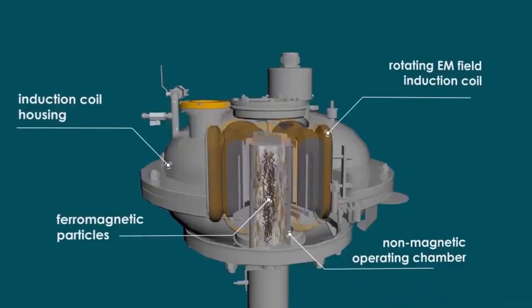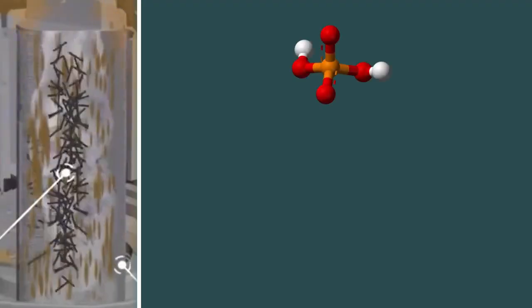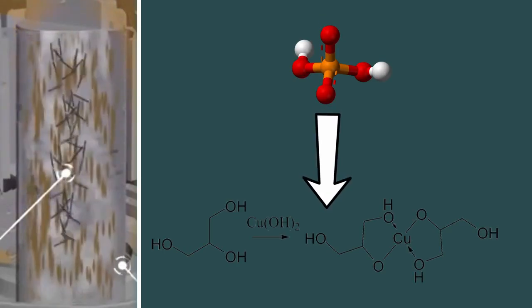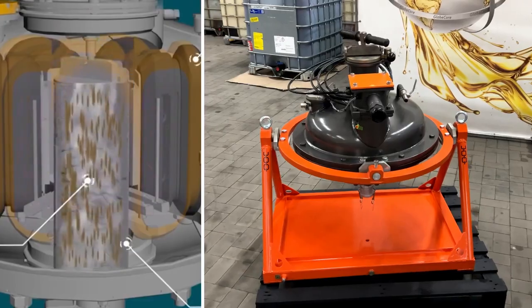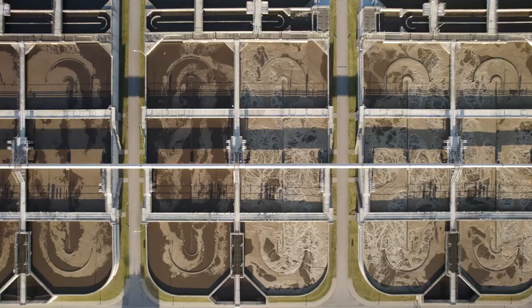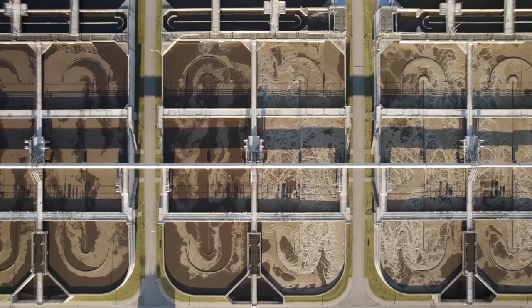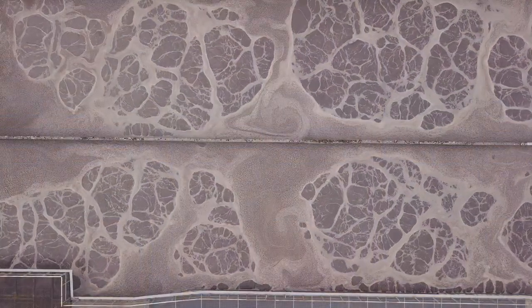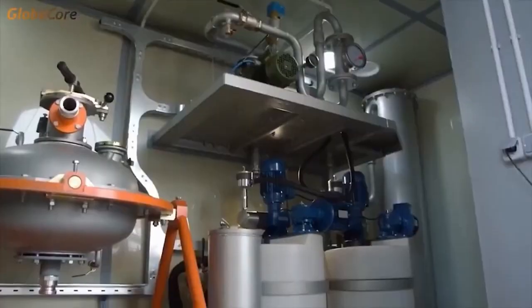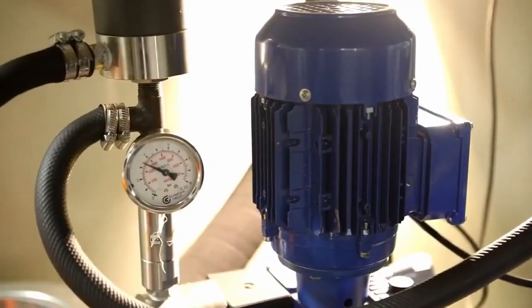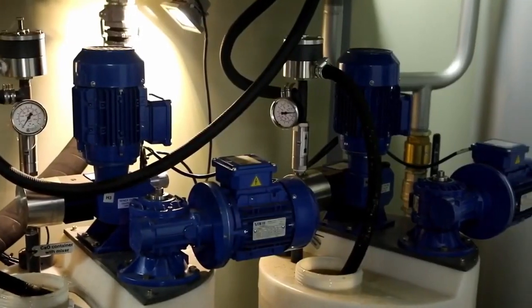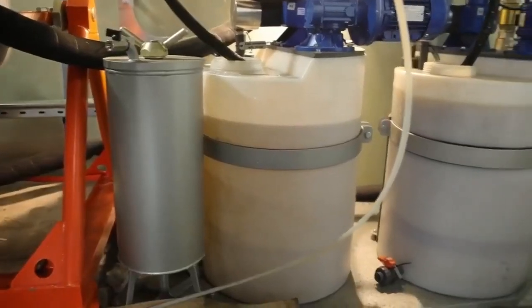While in operation, the vortex layer machine ensures rapid mixing and dispersion, as well as electromagnetic processing, which facilitates the defluorination and conversion of phosphates into water-insoluble compounds. The treatment takes 1 to 3 seconds, after which the wastewater is transferred to a clarification tank. The consumption of wastewater and lime milk is monitored by flow meters, and the pH level of wastewater, by pH